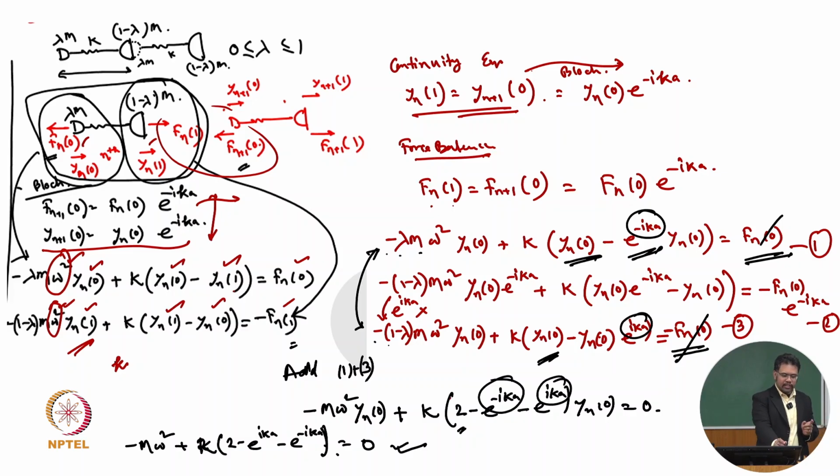If you see here, what is the degree of freedom for this unit cell? 1. It is mass and spring, so it's a single degree of freedom, and the connection is also single degree of freedom. How it is connecting with the other is also single degree of freedom. So once it is single degree of freedom, single Bloch theorem will be used twice.